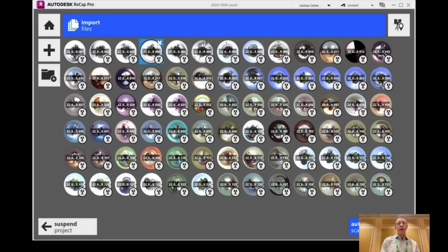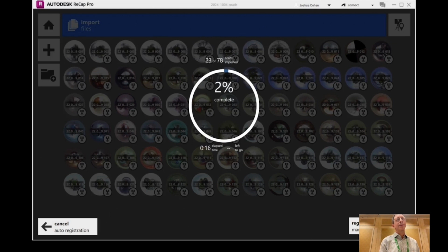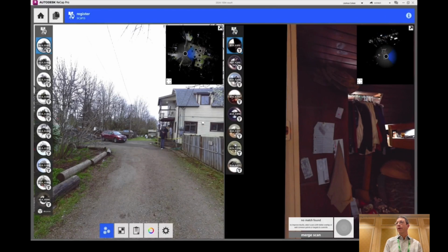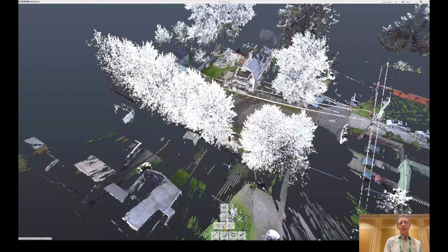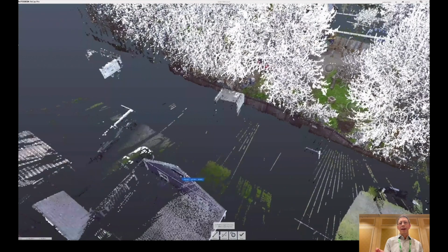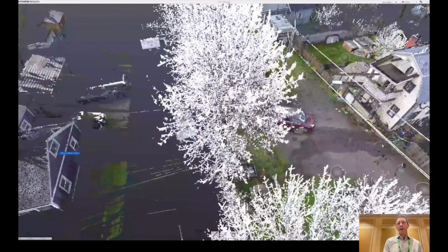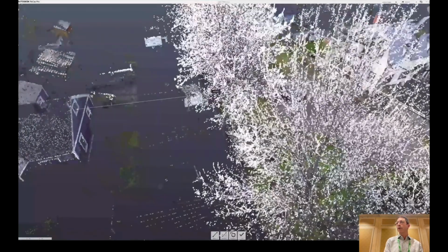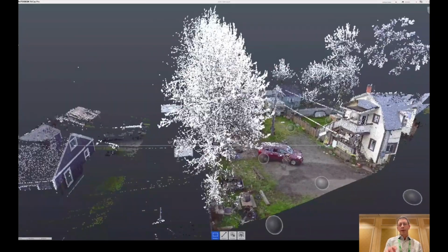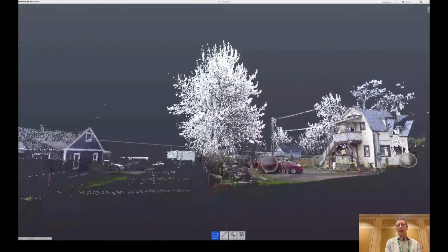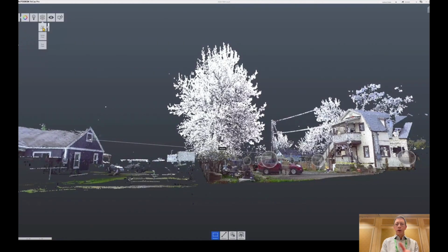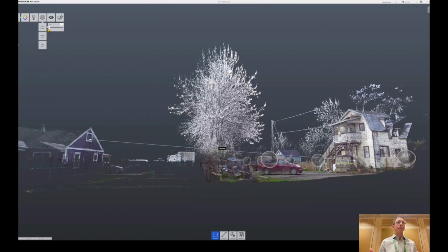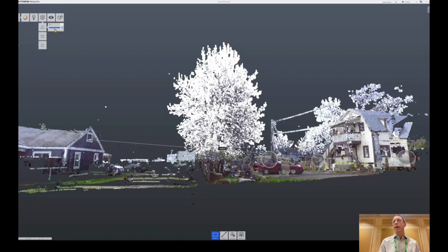And we have for a long time used Autodesk Recap mainly as a way to take scans that come from different vendors: Trimble, Faro, Leica is not great for opening in Recap, but trying to get scans from different places and figure out how do we get those registered if they are not already registered. How do we crop it down to what we need? We can adjust the point size as we need to, and do things like measure from side to side. For this case, we needed to know how far apart the houses were, and more critically, what's the difference in elevation.